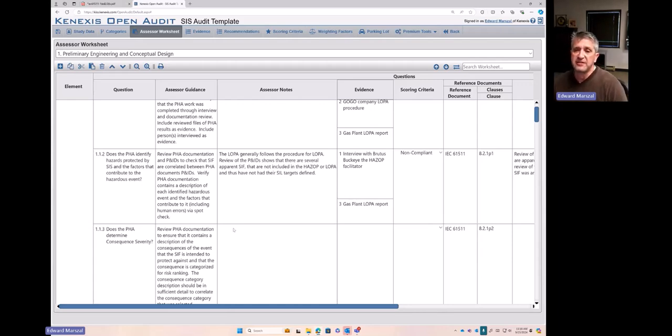The functional safety assessment needs to be done by somebody senior, somebody competent, and somebody that's independent of the work. We want a hands-off, cold eye review of the work activities that occurred. We need to plan what stages we're doing for the functional safety assessment. There are 5 of them.